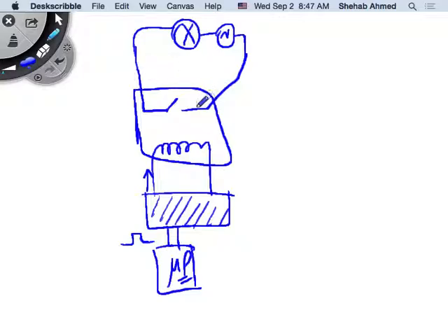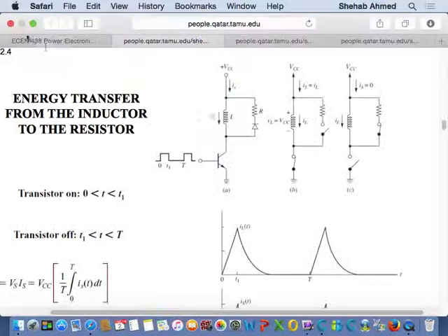And this is very commonly used in motor robots for running motors and turning off motors and flipping their direction, right? If you want to flip a direction of a motor, you want to flip the direction of the source. So you maybe connect the battery through some relays to the load. Some of these relays have multiple contacts. So one contact will turn off, one contact will turn on, for example, when you energize it. So you can build some intelligent circuits around relays. You can build something like digital circuits around relays. But that way you can control power in a certain way, right?